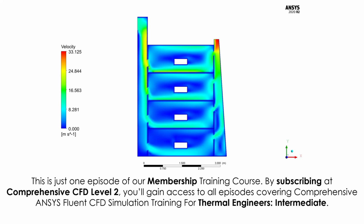And now in this slide, you can easily see the velocity distribution inside our computational domain. The airflow will enter this 4-story building from the top left inlet and then will exit our computational domain through the top right outlet.